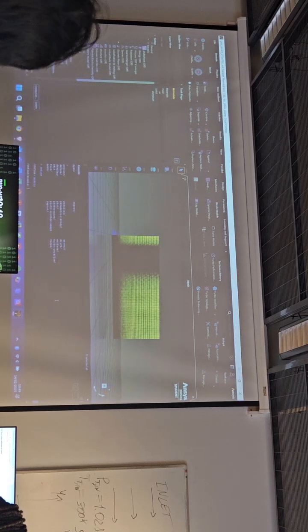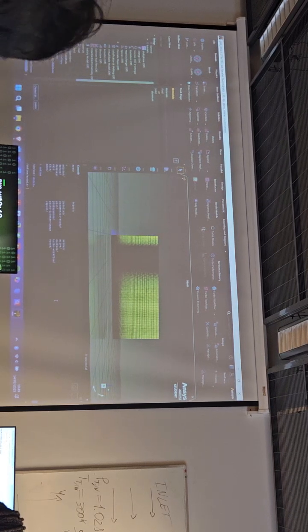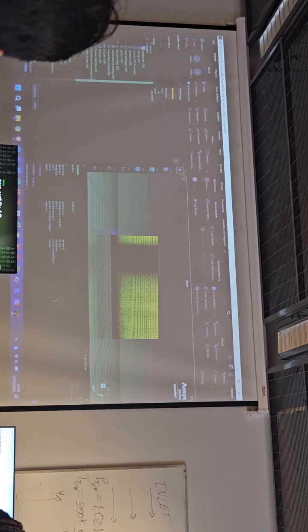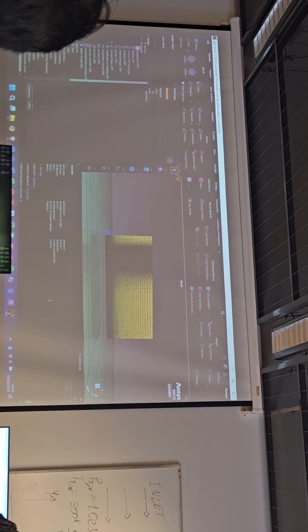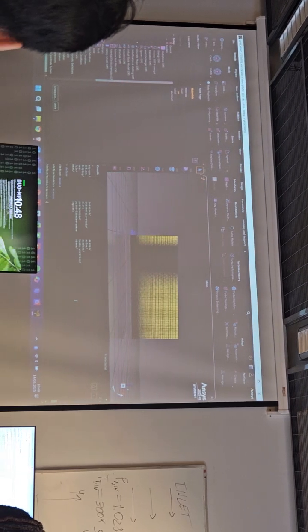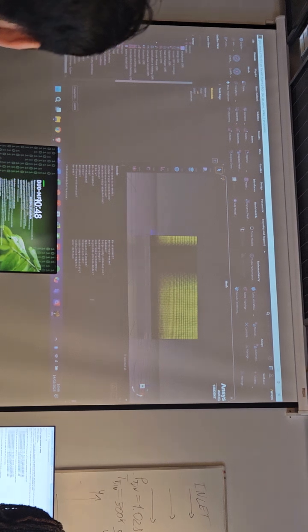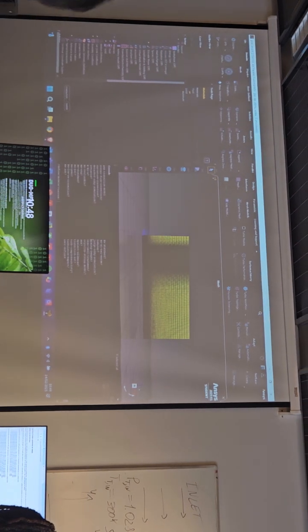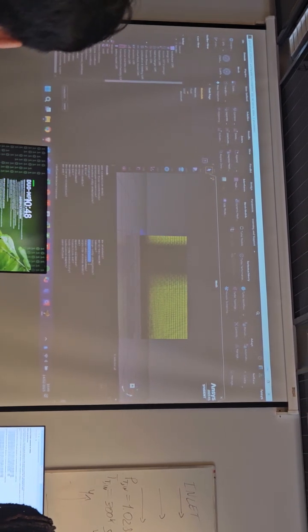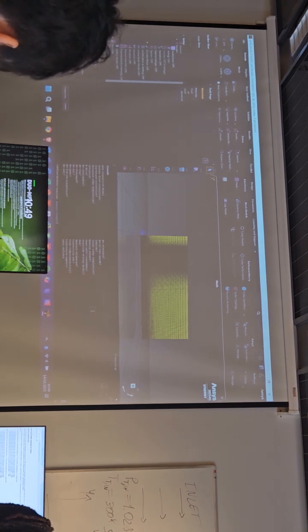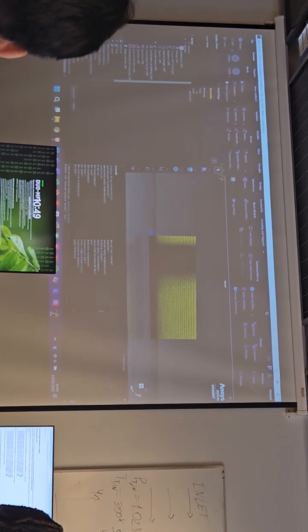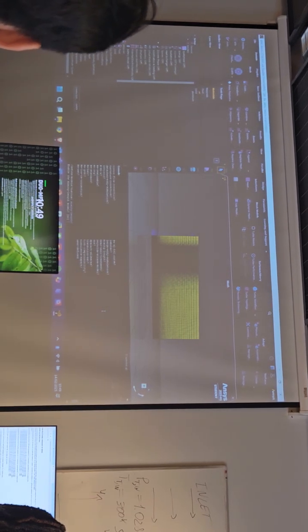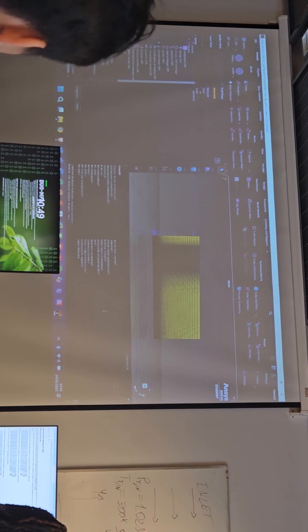I will write this also on the whiteboard so that you can follow the path. Then viscous. And in viscous, if I click enter, here I can see all the options. And there is an option written mixing length. So we copy this and enter. And then I'm asked if I want to enable the mixing length model. And I say yes.